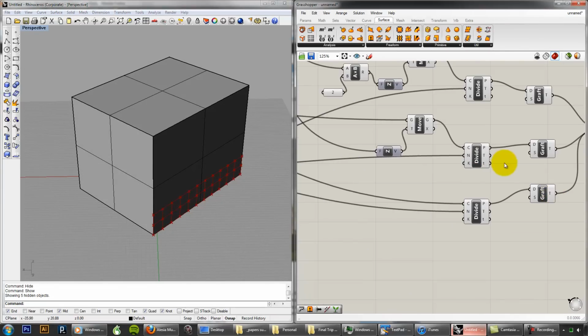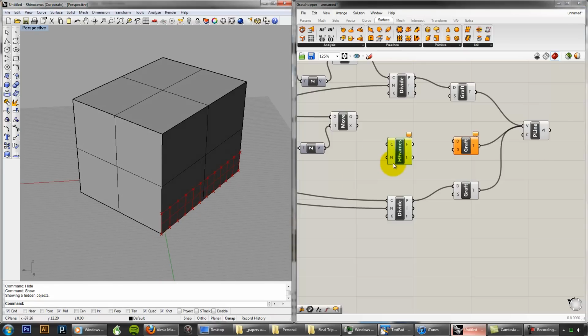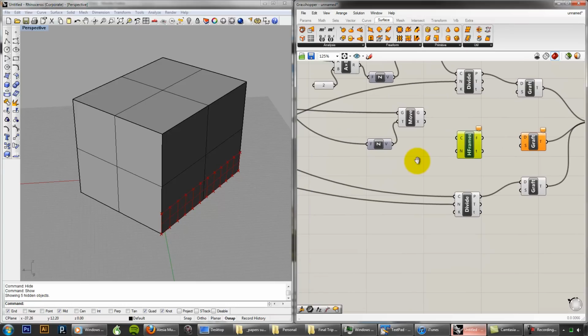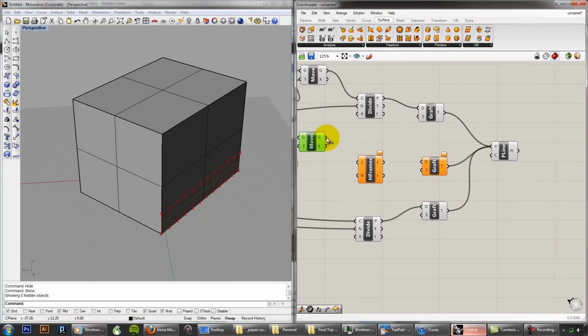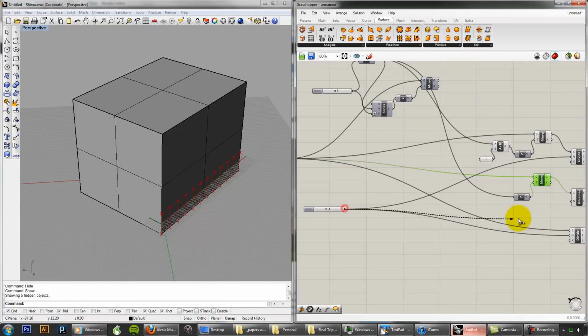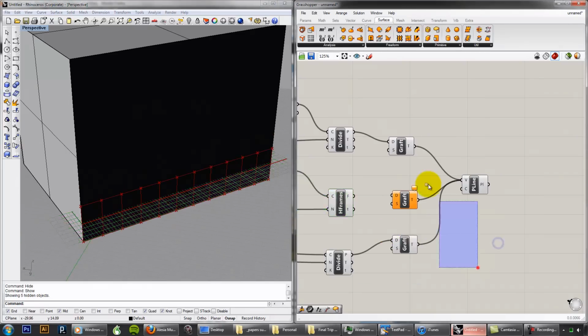What we can do is, instead of using a divide here, we can make a set of horizontal frames. Remember, horizontal frames go along with the angle of a line, right, of a vector. And so they are going to adapt to the angle, and they're going to allow us to perform some transformations on those points. So what I'm going to do is, this is the curve. I'm going to create a series of horizontal frames on that curve. I'm going to make the same number of frames as I had points. This might get a little confusing here. Let's get this out of the way.